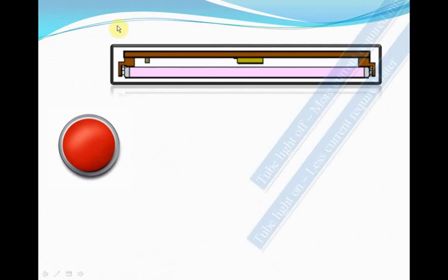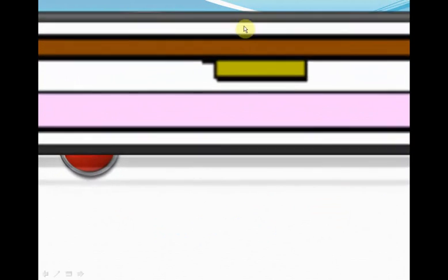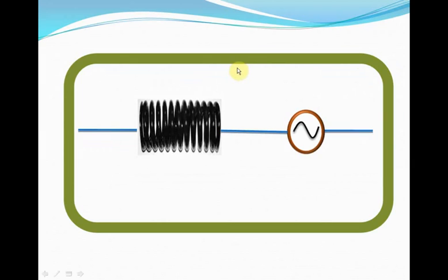So here we go. If you magnify this picture, this is what is inside the choke coil. There is this inductor and there is this alternating voltage source, and that is all. So what you really must remember about the choke coil is that it is used to reduce the current while it keeps the net power consumed the same, and makes use of the fact that the net power consumed in an inductor or a capacitor is 0 on an average. And this concept actually brings us to the end of the chapter relating to alternating current. There we go.